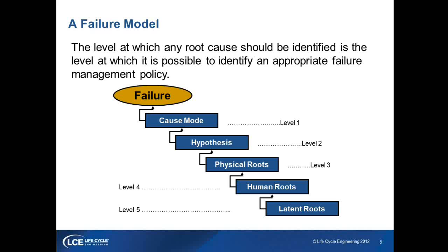But if I address and put actions in place to address that bearing failure or that shaft failure, that's a very limited level of analysis, a limited level of corrective action moving forward. That one action or two actions, let's say I put it on a vibration route or change my lubrication every so often, that addresses that one small event, that small window of failures for that one specific piece of equipment, but what it doesn't do is address the potential overarching human and latent roots that exist. And that dives deeper to our level 4 and level 5 issues.